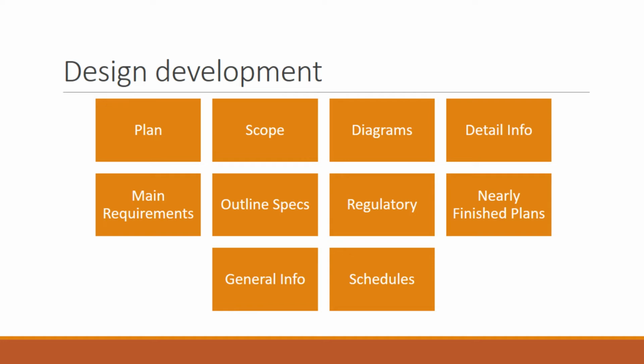Now, depending on the complexity of the project, the aforementioned deliverables account for roughly 20 to 50% of the design effort and are subject to an estimate error of around plus or minus 10%. Major design decisions and calculations must be completed in order to reach this estimate's accuracy, and qualified individuals are required to carry out the estimate. Architectural and engineering firms are frequently great at defining the scope but terrible at estimating. On the other hand, construction companies frequently excel at cost estimation but struggle with scope assignment.